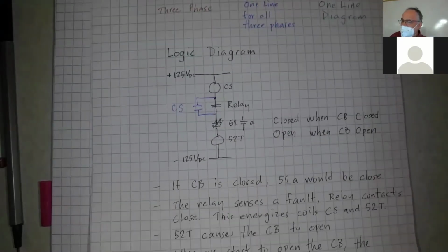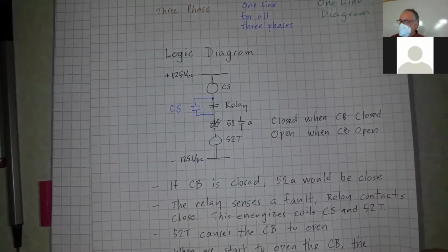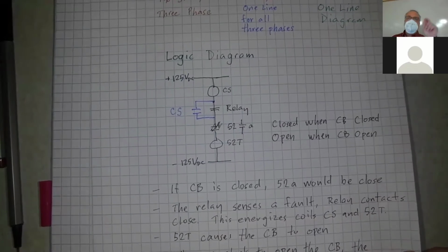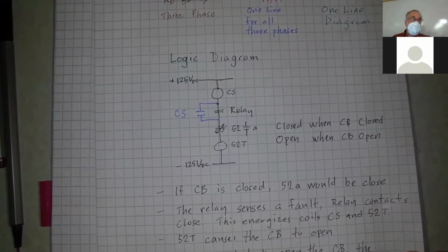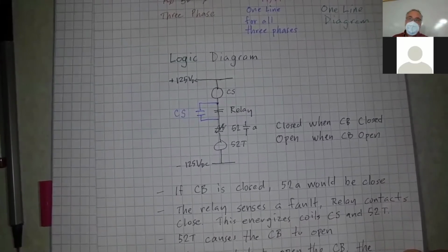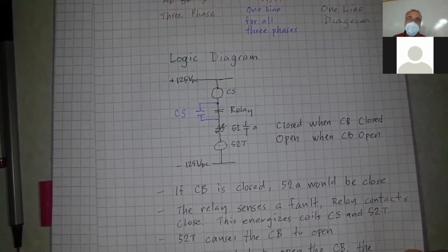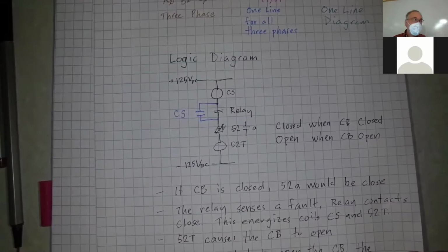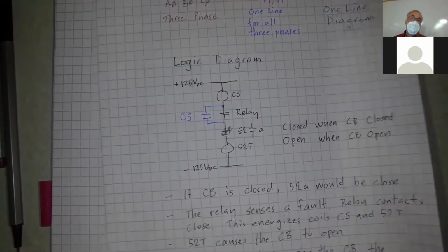Any questions on how this relay logic works? Like I said, in microprocessor-based relays, you can keep a time on there that it will stay high. So once it says to trip, it'll stay in the trip position for a second, which will give the circuit breaker plenty of time to open up. That's 60 cycles, right? So the breaker should be open by then.